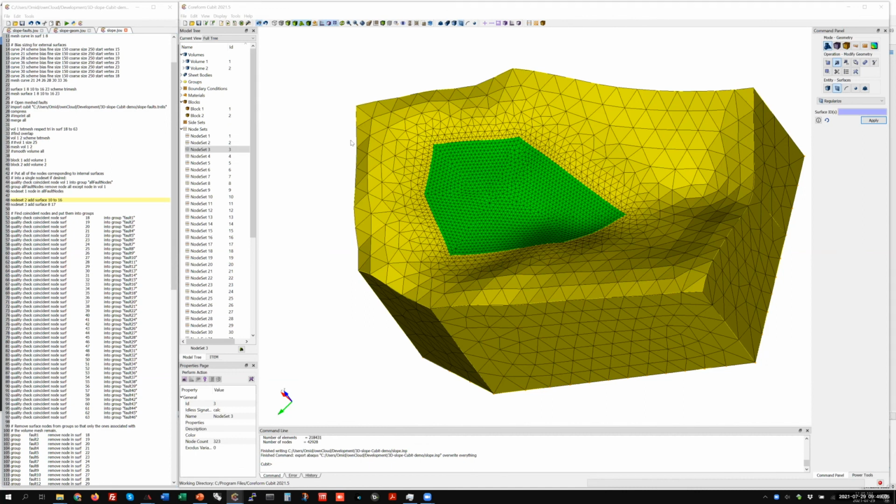So it was always superbly easy for us. It was just fine-tuning our import functionality for the specific Abaqus formats that Cubit was writing, because the Abaqus format is not really global. The element types and so on change in the INP file, but that's a relatively easy change to make. So for us, it's always worked very easily because we could directly import from Abaqus.